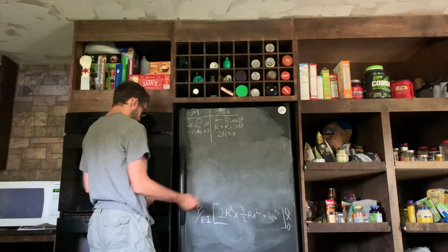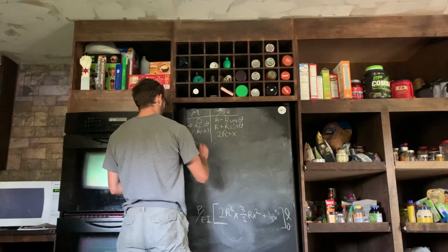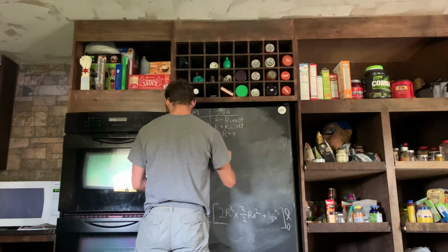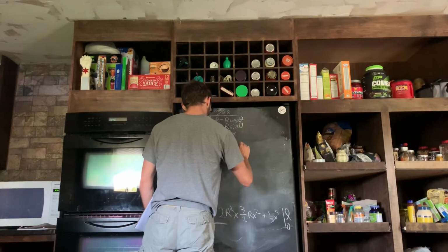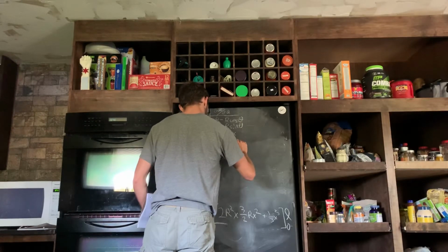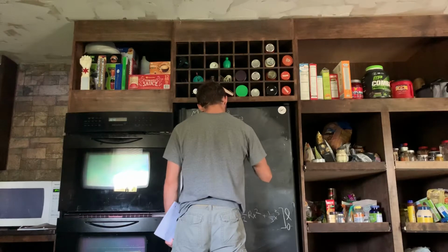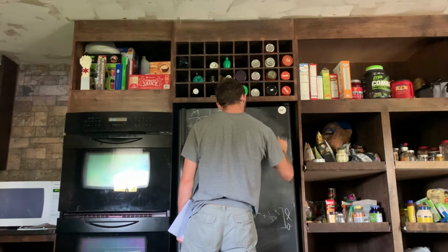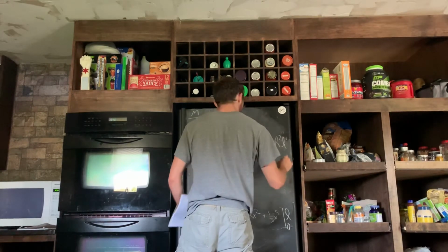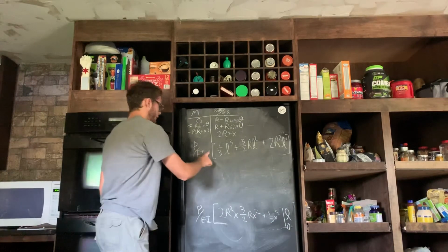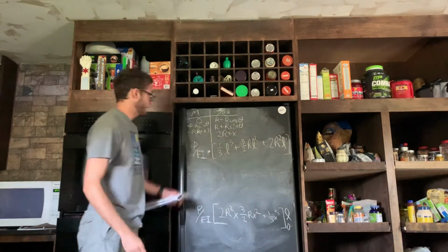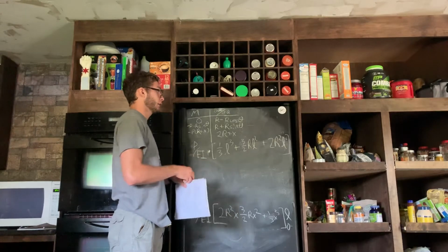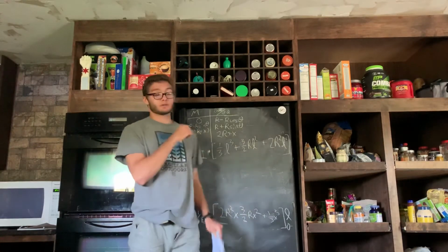Plug in, and we can simplify this a little bit, so then we get P over EI is equal to 1 over 3 L cubed plus 3 over 2 R L squared plus 2R squared L. And this would be times P. And that would be the deflection on D caused by all the parts combined.